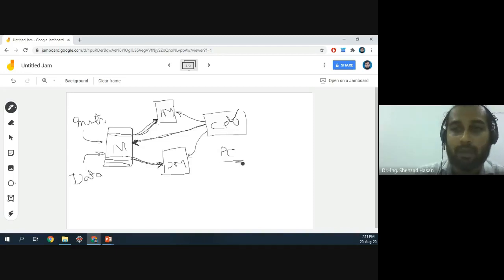The program counter is the only register holding the instruction address, while data addresses can be stored in any temporary register, or a combination of register plus an immediate value. So this goes to some temporary register internal to the processor, and from there it generates the address.